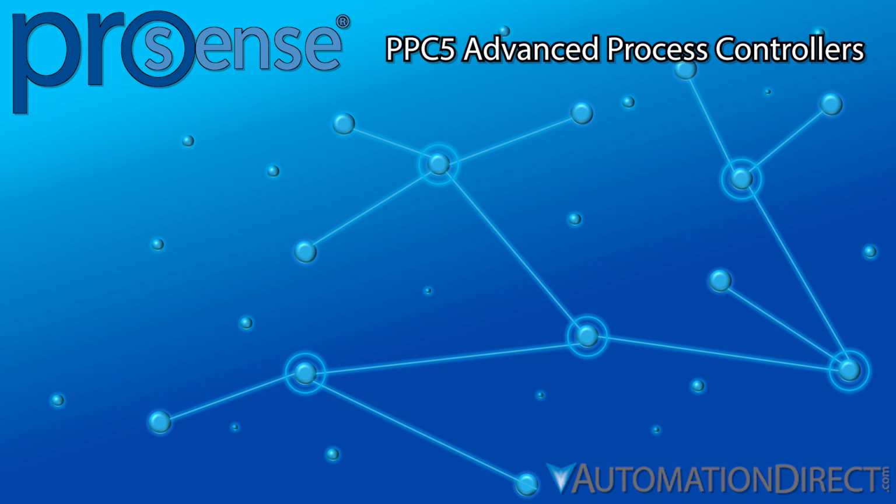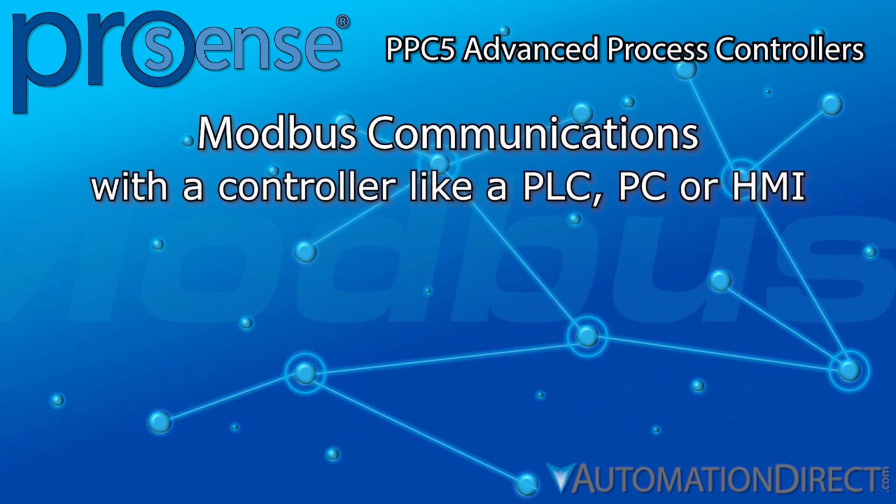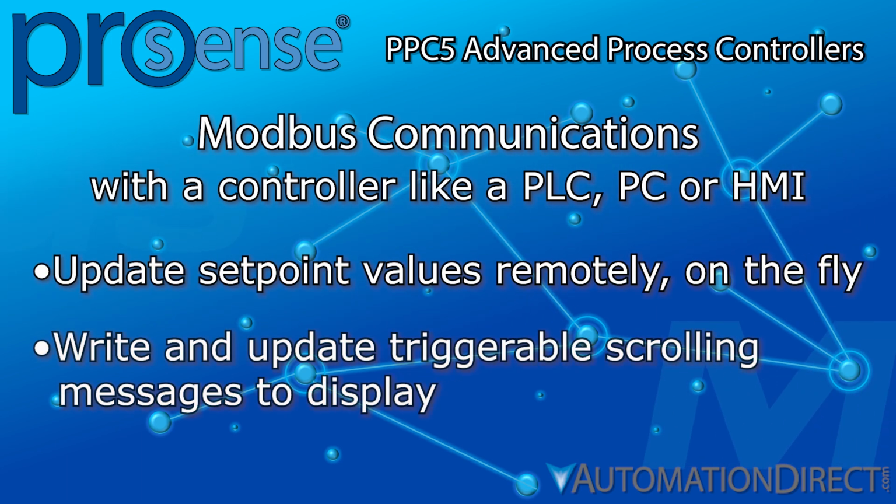One of the features offered in several models is Modbus communication, RTU serial over RS485 or Ethernet TCP. Using this communication ability, a controller like a PLC, a PC, or an HMI can change remote settings or send a custom scrolling message to be displayed on the PPC5.